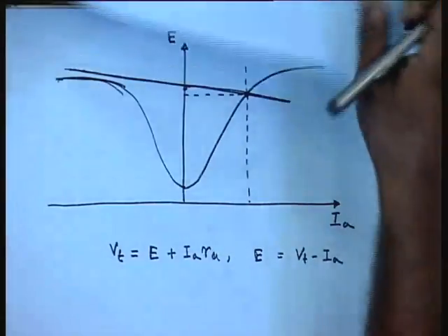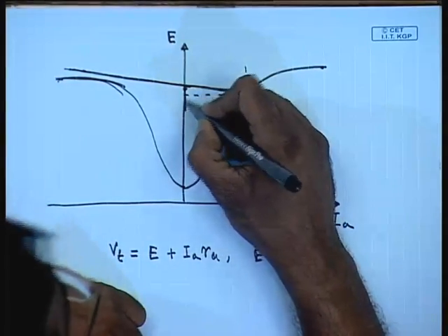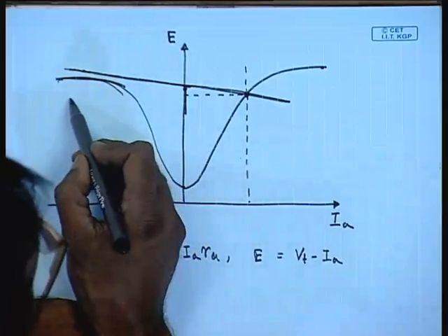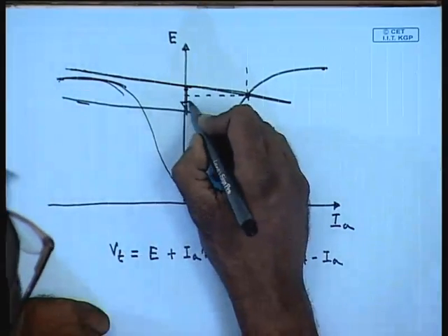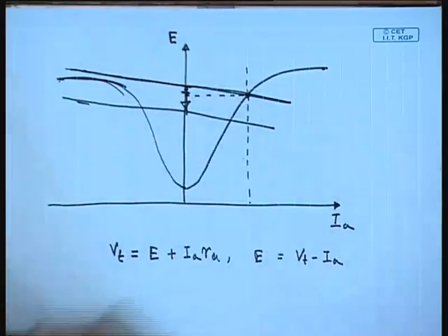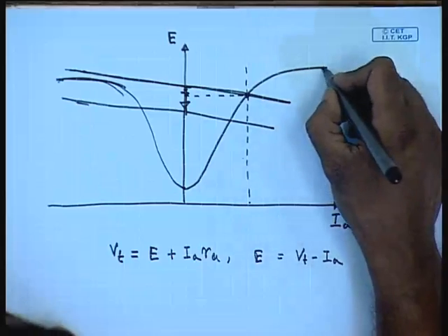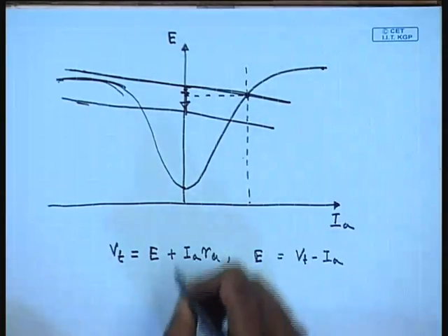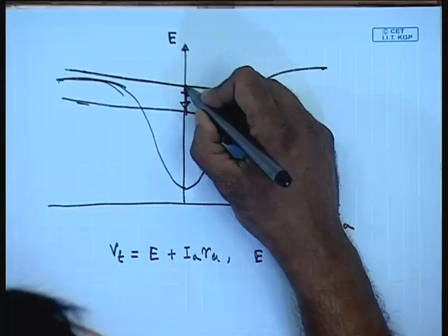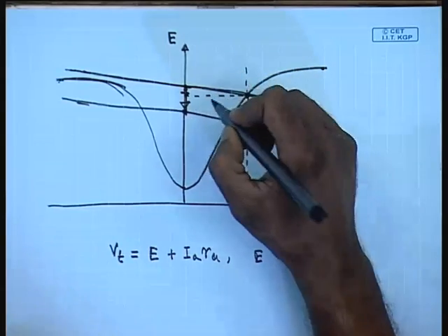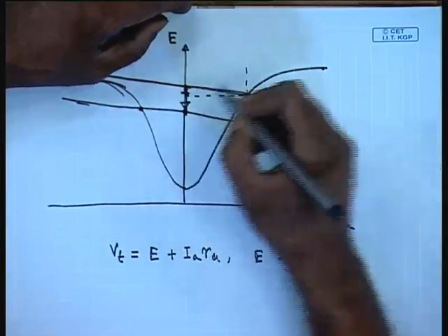The only way regenerative braking mode is possible is if by some means the load line can be reduced during braking operation. As we will see again, this can be achieved by using an electronic power supply called the chopper. Hence, normally a DC series machine will not allow regenerative braking, but using a chopper you can go for regenerative braking of even a DC series motor.